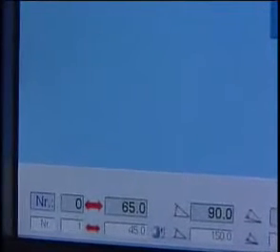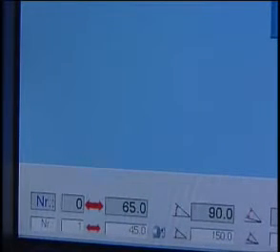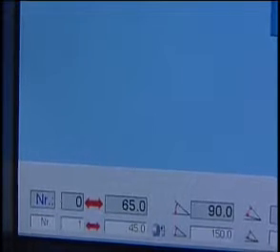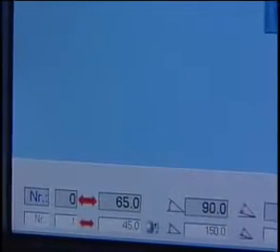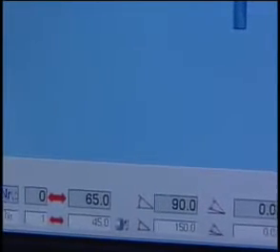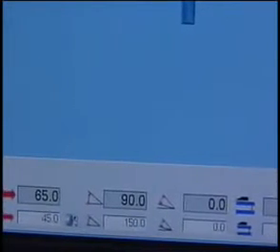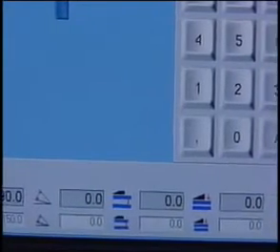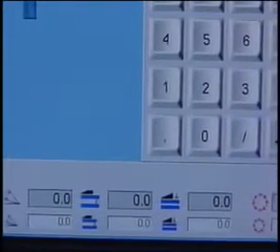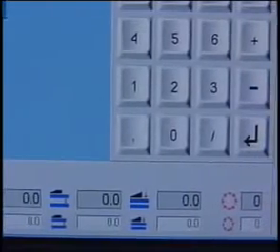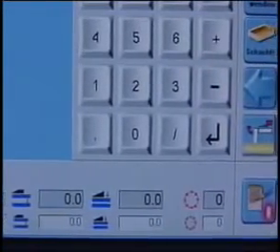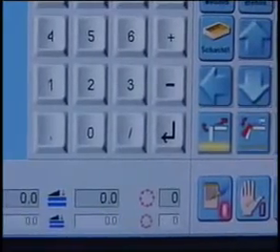At the bottom of the screen, you will find the actual and the following program line of the present profile. Each line has a subsequential number, value for the back gauge, symbols for material rotations, and a column for the bending angle. The bending angle correction compensates for the material spring back when doing radius work. Upper beam lift up is important when parts must be turned around. And so is the column for open hems, and the final column for the number of loops to form radius.